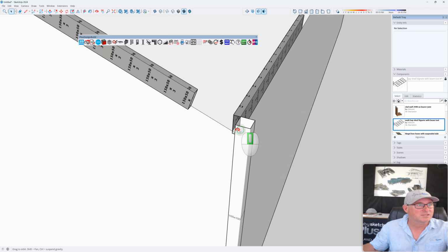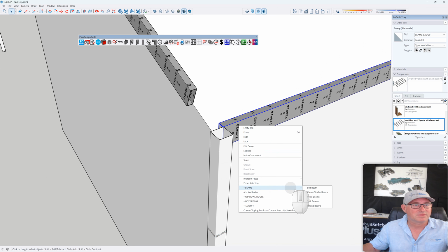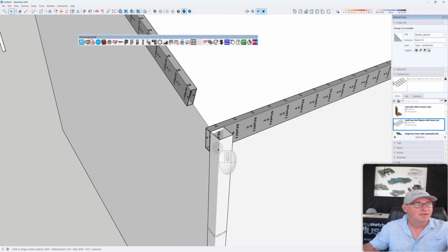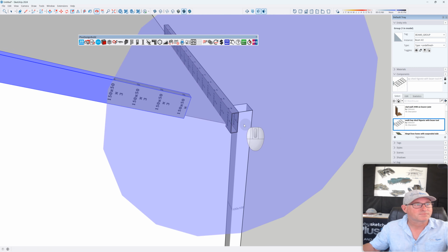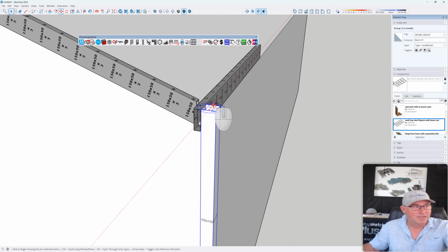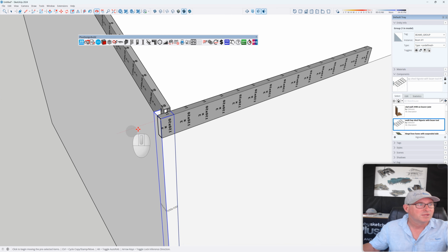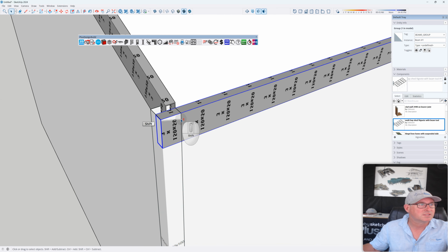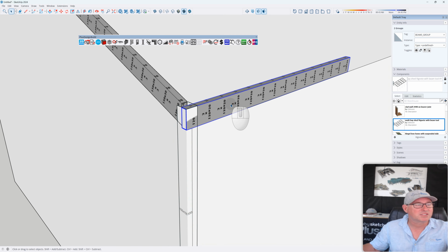And you can see there that I need to get that to go through. So right click, beams, extend beams. Yeah, and right click, beams, extend beams. Now obviously you can make these intersect or miter or whatever it might be. Right, you might say that the post really needs to be in here and it's going to be scalloped later. Whatever it is that you think that you need to do. And really I should move this and the post back to here, so it lines up with the rafter. Right, now I can go and change the sizes and so on.